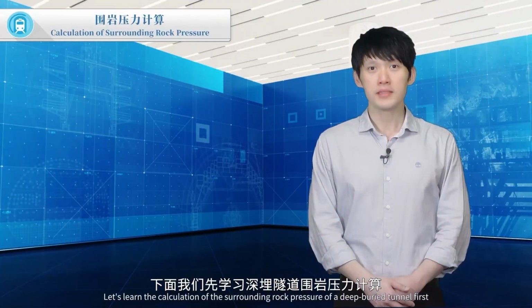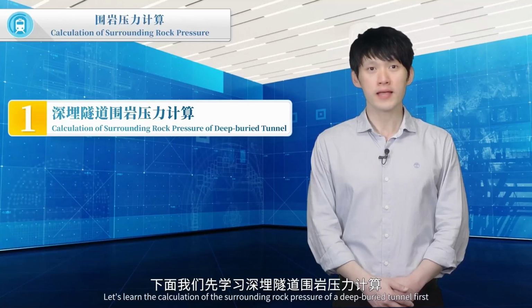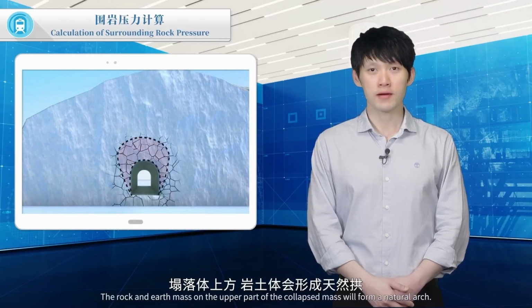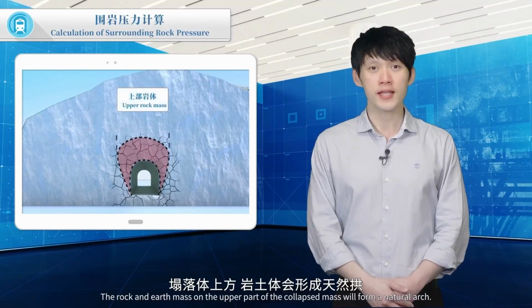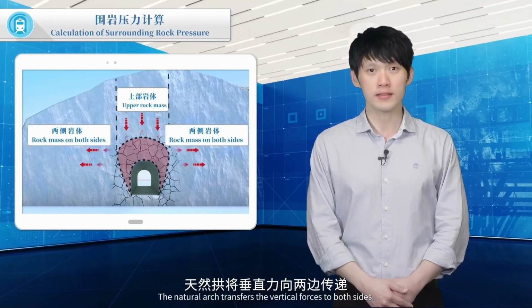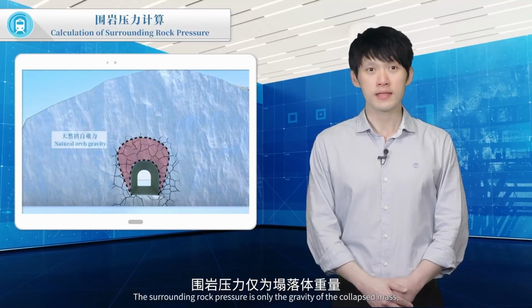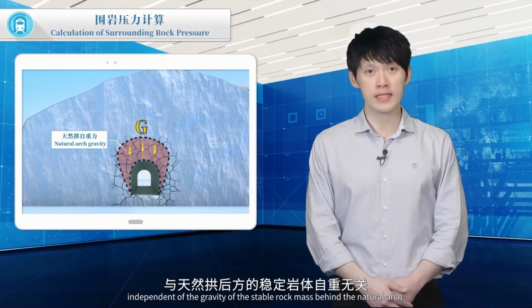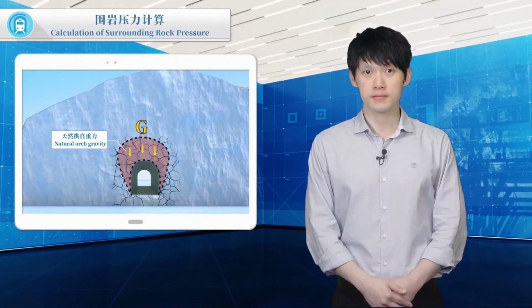Let's learn the calculation of the surrounding rock pressure of a deep buried tunnel first. Due to the arching effect, the rock and earth mass on the upper part of the collapsed mass will form a natural arch. The natural arch transfers the vertical forces to both sides. The surrounding rock pressure is only the gravity of the collapsed mass, independent of the gravity of the stable rock mass behind the natural arch.